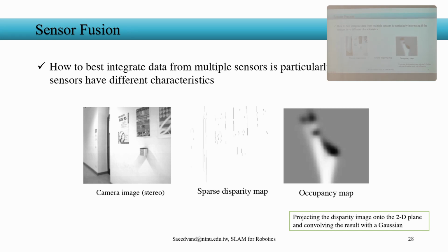In today's course, we only talked about occupied or not occupied for one cell. We didn't say that if we apply a Gaussian model over here, it not only changes the probability here, it changes the surrounding grid cells too. That can be called applying the Gaussian on the occupancy grid map.